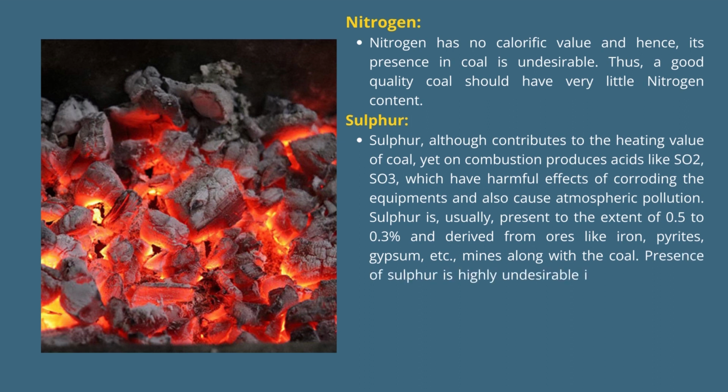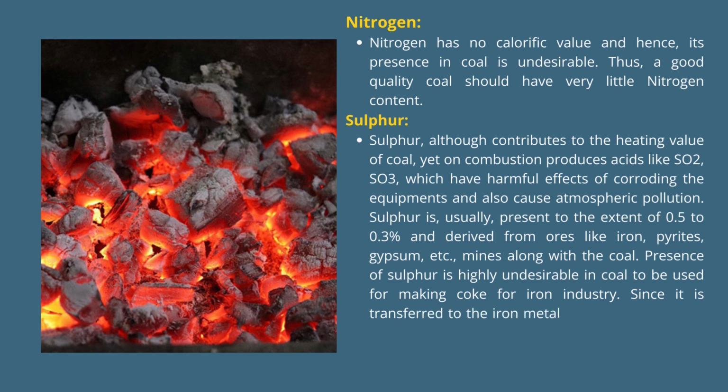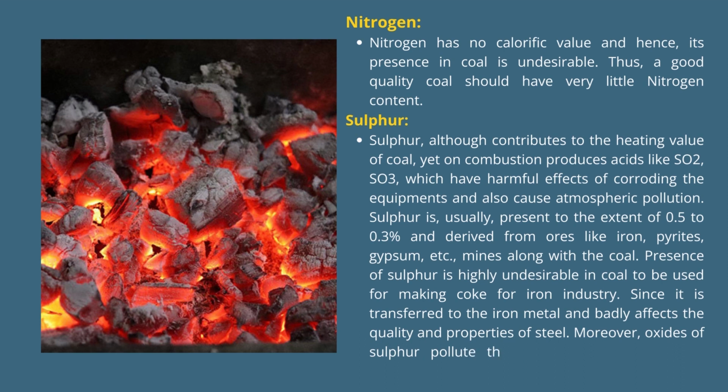Presence of sulfur is highly undesirable in coal to be used for making coke for the iron industry, since it is transferred to iron metal and badly affects the quality and properties of steel. Moreover, oxides of sulfur pollute the atmosphere and lead to corrosion.